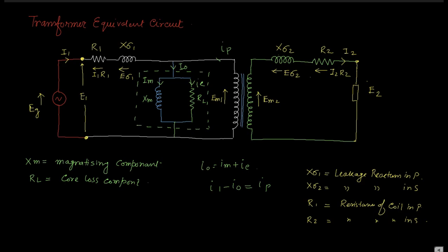That's why, if we put this in series, then if I1 is 0, this whole thing is 0, that is there is no existence of the transformer's equivalent circuit. So now if you consider this entire diagram, this part is nothing but the ideal transformer, and this part is the equivalent circuit for the primary side winding.